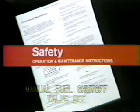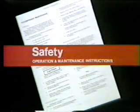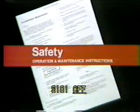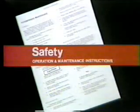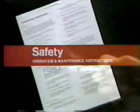Always lock out the electrical starting circuits by moving the system's control switch S101 to off and tag Danger, Do not operate, to prevent unexpected starting of the engine. Review the safety precautions and procedures in the operation and maintenance instructions before beginning this procedure.